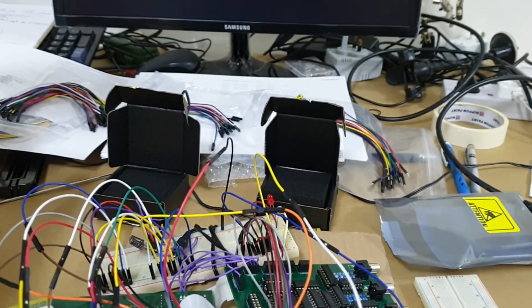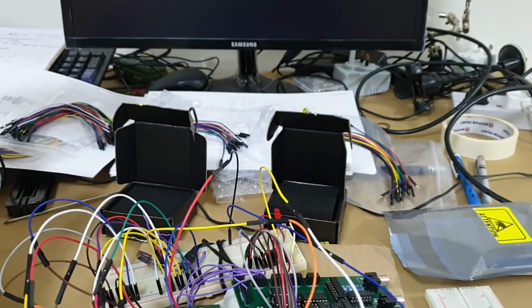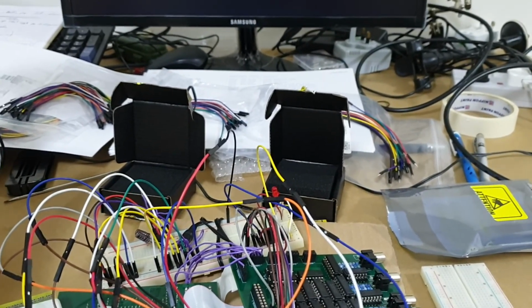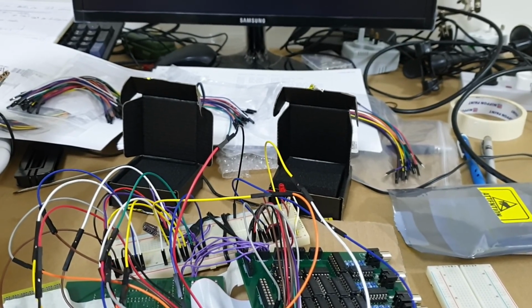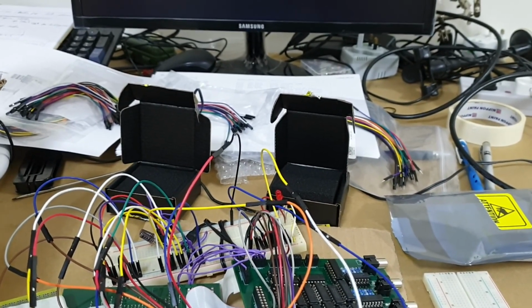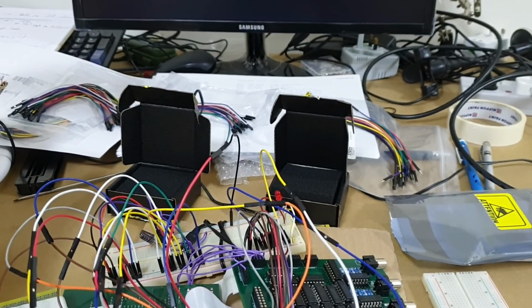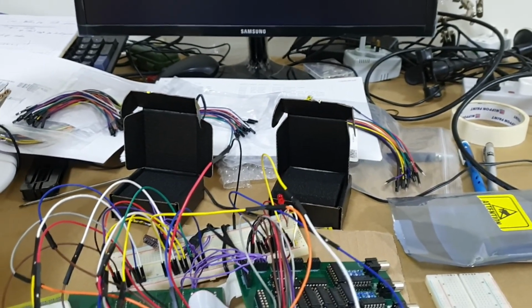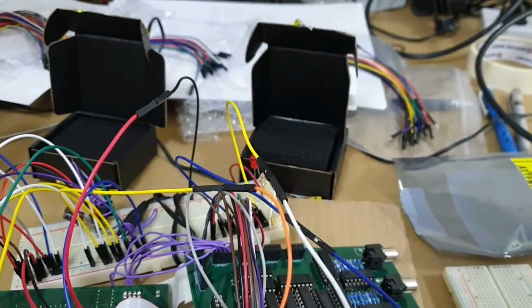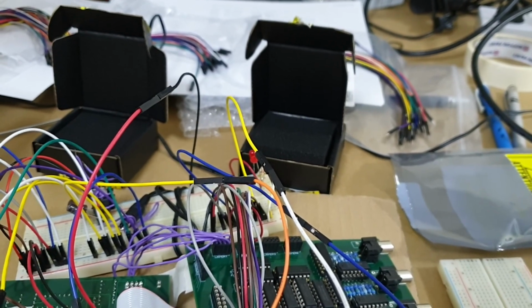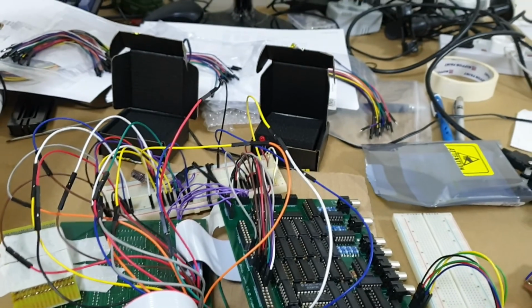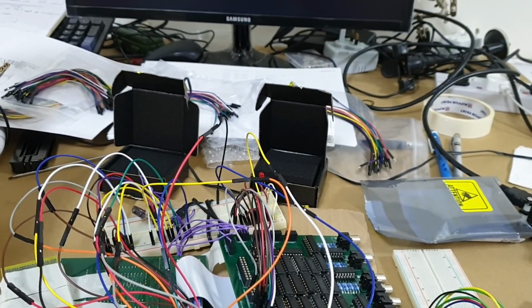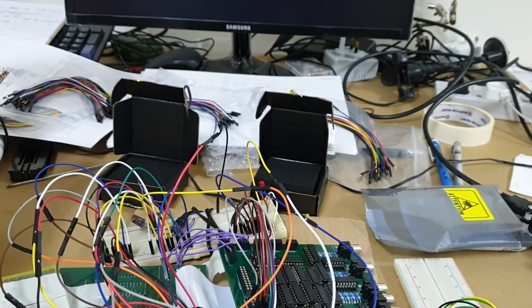There's the top and bottom borders for 16 by 16 pixel sprites, and I think if I remember rightly, the addressing for the screen and the character and color memory doesn't quite start from the very first address, which is 9000 in hex. I think 9040 was the first top left hand corner character that could be visible in the hardware simulation. So anyway, we'll see.